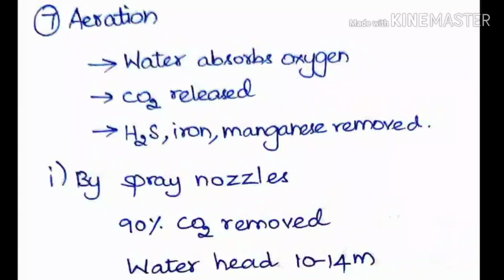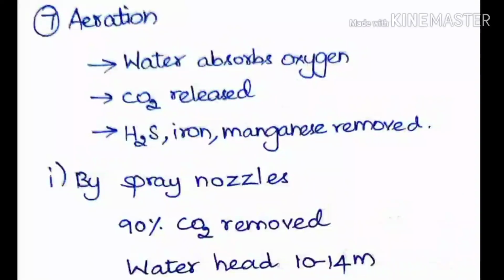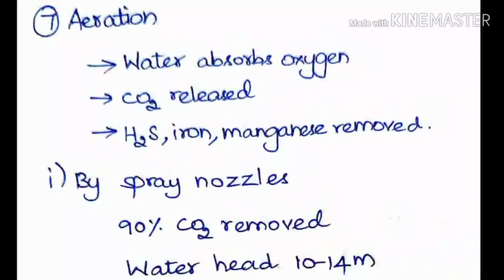So when it is aerated, the water absorbs the oxygen and CO2 will be released there, and also other unwanted gases will be released there. H2S, iron and manganese could also be removed by this aeration method. So this can be done by various methods.